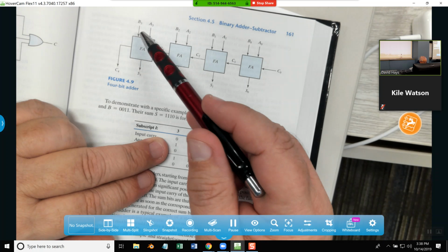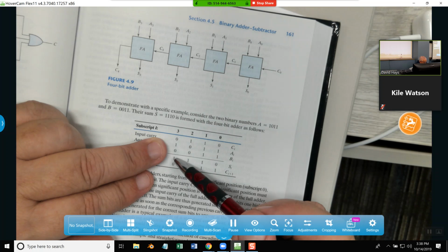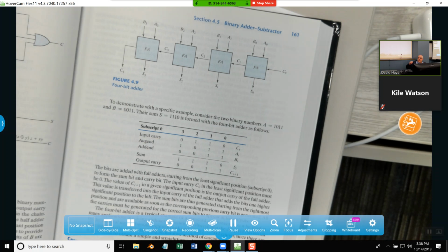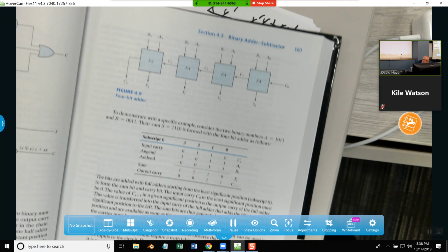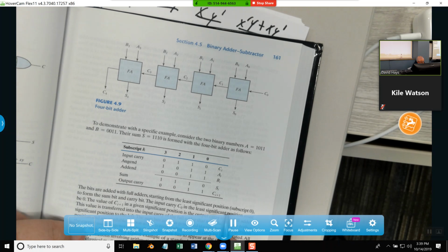Carry propagation. Addition of two binary numbers in parallel implies that the bits of the augend and addend are available for computation at the same time. As in any combinational circuit, the signal must propagate through the gates before the correct output sum is available in the output terminals. Total propagation time is equal to the propagation delay of a typical gate times the number of gate levels in the circuit.